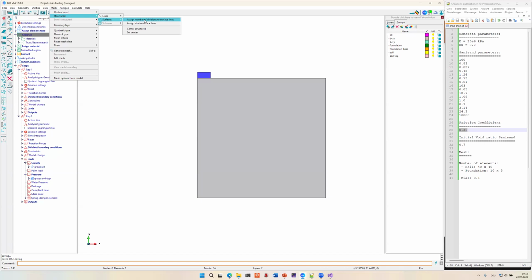That means we say how many nodes we have on the lines of the surface. You could also prescribe a size if you want. You could also leave the mesh completely free for GID to generate. So there are a lot of options. I'm making it maybe a bit more complicated than necessary now, but just to show you the different features that you could use.